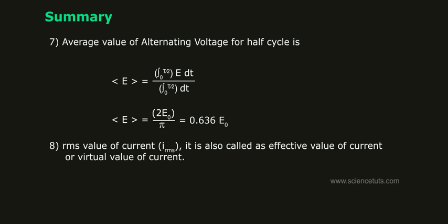8. RMS value of current, I RMS. It is also called effective value of current or virtual value of current. I RMS equals root of average I square.